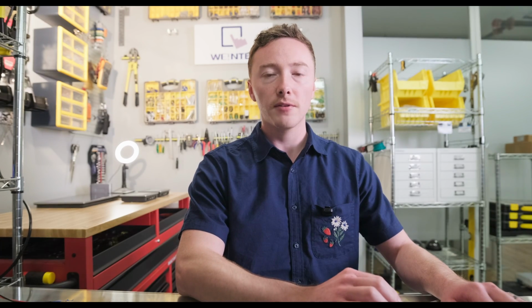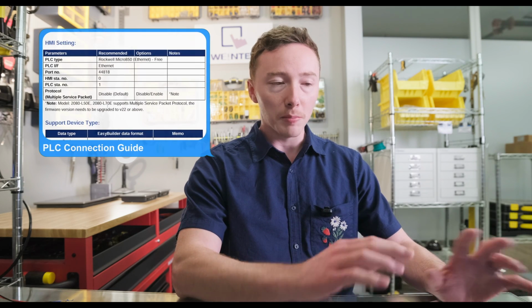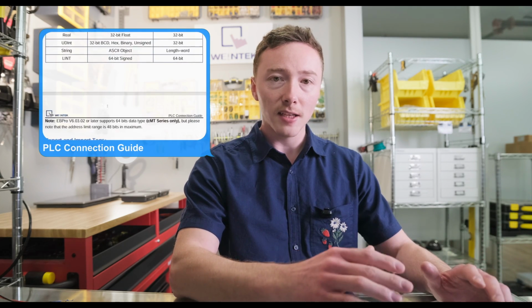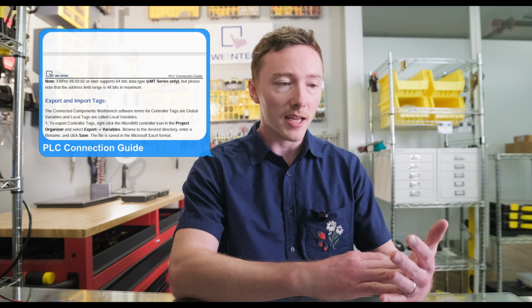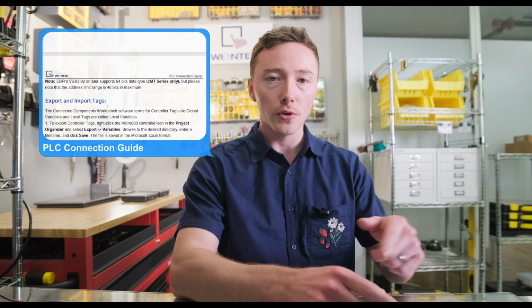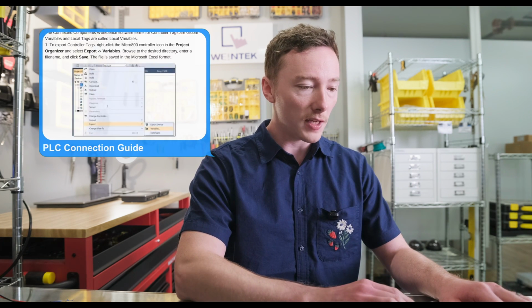So I'm going to open our computer that has Connected Components Workbench and EasyBuilder Pro. And the reason why I'm not worried is because we have a set of PLC connection guides on our forum, on our website. You can find them in both of those locations. They're detailed guides that typically go over the step-by-step instructions to connect our software to your third-party device. And we have one right here for the Micro 850 I'm going to reference.